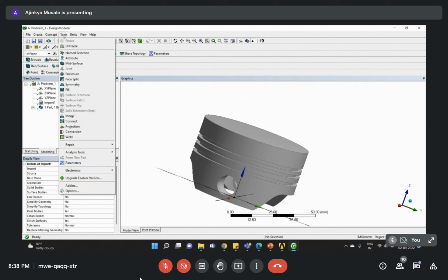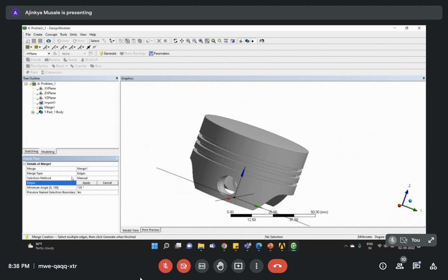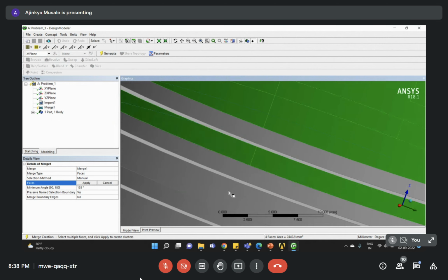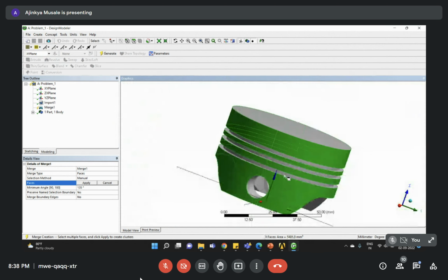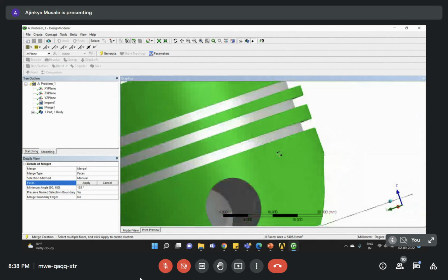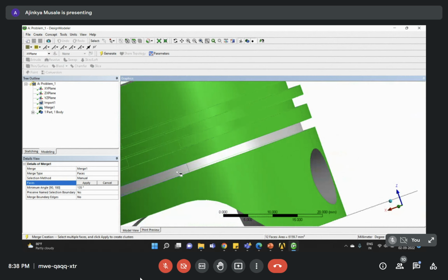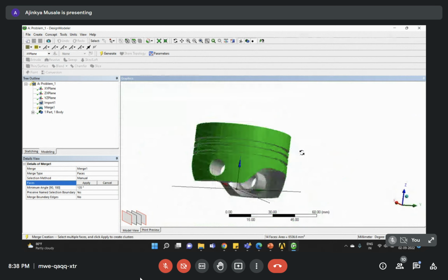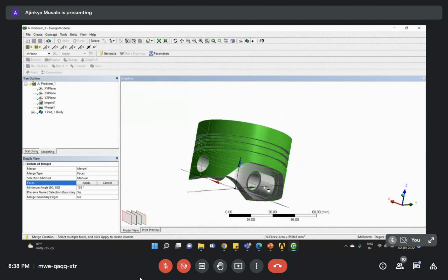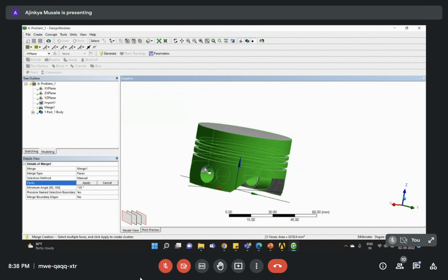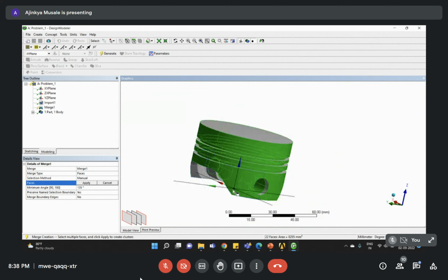You have one option, just merge faces. So there is one option that you can use. So instead of edges, just select faces, and you can select such faces which you do not want to have such edges in, or inside also I'm having some area I saw over here. So what I have done is I have simply added all the faces which I need to merge. So maybe somewhere here and this one.